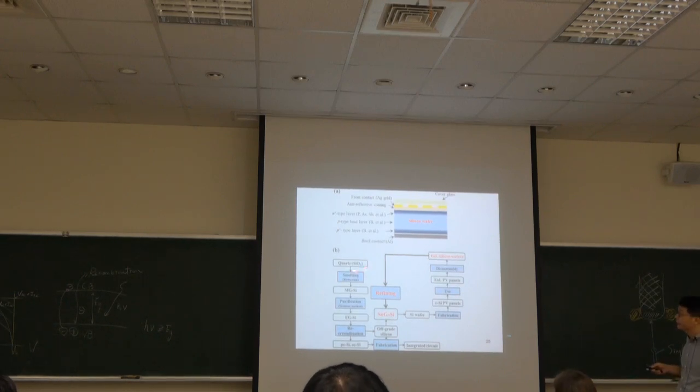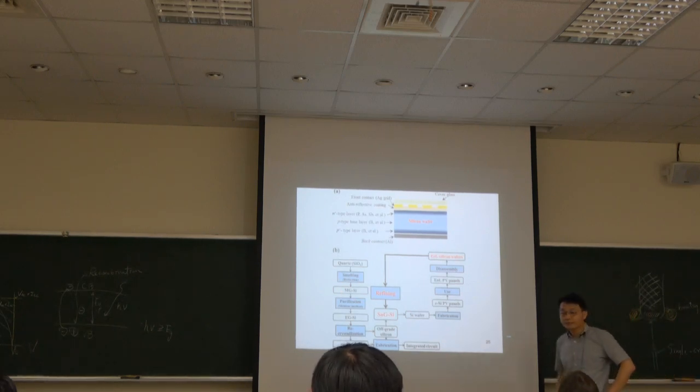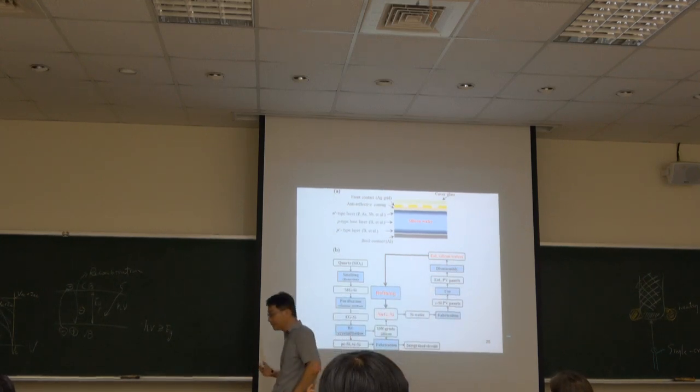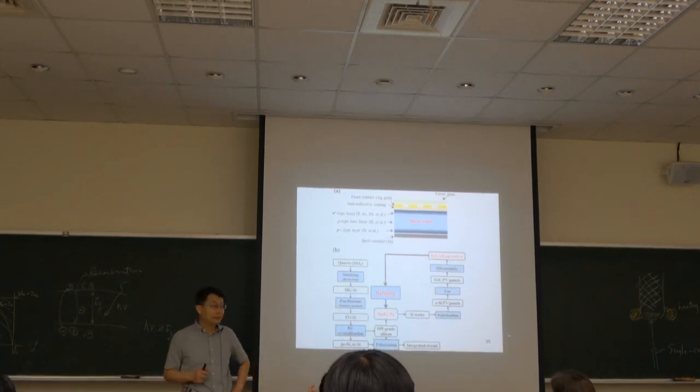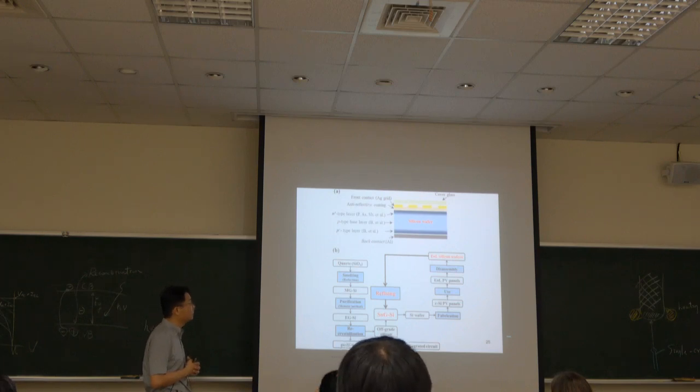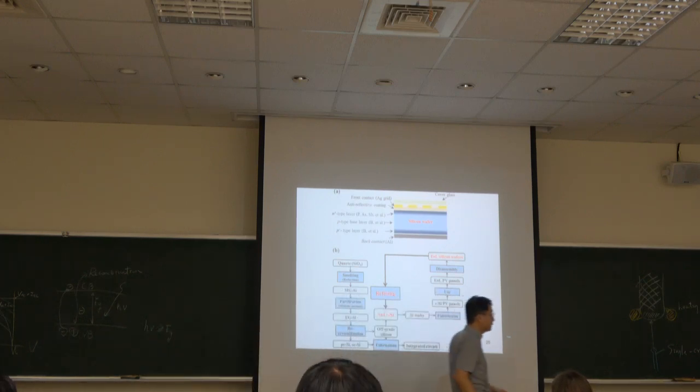While cutting the wafer, we still have to think about how to purify the silicon, because using this kind of process still has impurity that may be doped into the material. So we have to refine it. Refining requires a process we call the zone refining process.